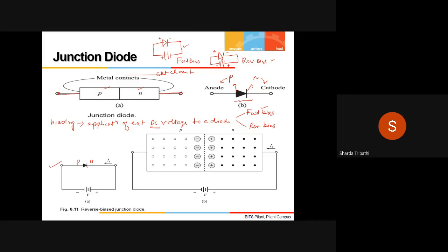So now what happens? Let us visualize this diode in the form of a PN junction, as shown in this adjacent figure, again in a reverse bias connection to the battery. In the last slide, what did we study? That the holes have the tendency to diffuse to the right and drift to the left. These are holes, just for clarity. This is my right and this is my left. So holes will diffuse towards this side and they will drift towards this side.